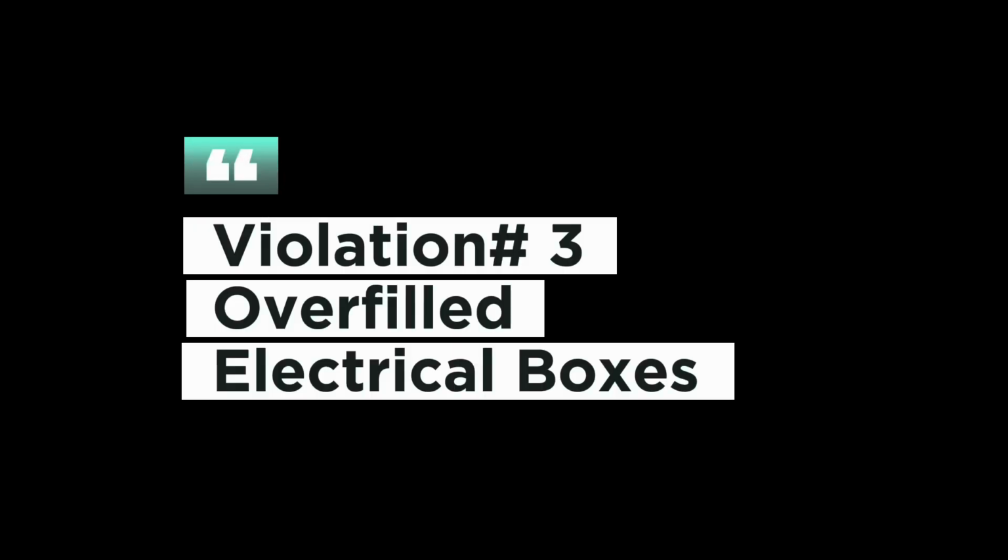Violation number 3, overfilled electrical boxes. It is important to have the adequate space for wiring and devices in all electrical boxes. An overfilled electrical box is a serious safety hazard. It can lead to loose wires, insulation damage because maybe conductors are too tight on some devices, potential short circuit or fires due to overheating. It's important to do a proper box fill calculation in order to have the correct space for wiring and devices in all electrical boxes. That's violation number 3 that we see often.